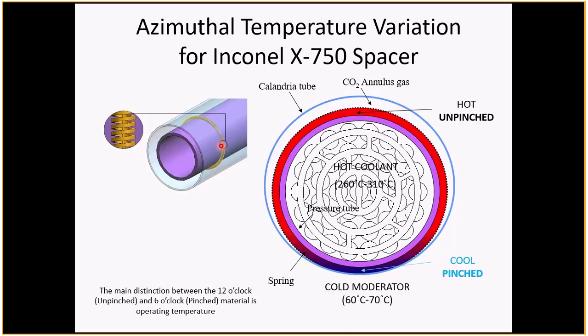And in the case of the first springs that were in use, which were Inconel springs, their design was a loose design and they moved very easily. And also there was concern that if it was an easily deformable material, it might yield. When you put a low yield point spring on this, there's a chance you may stretch it during installation and actually cause plastic deformation, stretch the spring, and it wouldn't be tight on the space on the pressure tube.